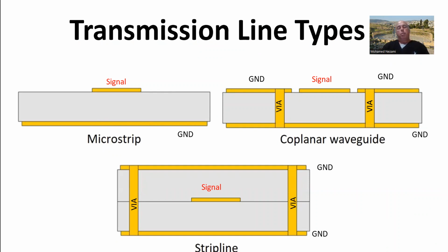So at that point, you will eventually have to specify and design a crossover, or what some people call a via transition, from a microstrip line on top to a stripline embedded between two ground layers in the middle of the stack layer. You have to design that, and once you design it once, that's it.